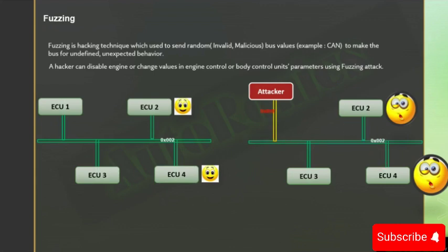I can give you another example. Let us say, for example, the vehicle is having electronic power steering. The electronic power steering will work based on the engine RPM. When the engine RPM is reaching more than 700 or 800, at least the engine is cranked, then the power control will be activated and you'll be able to steer smoothly.